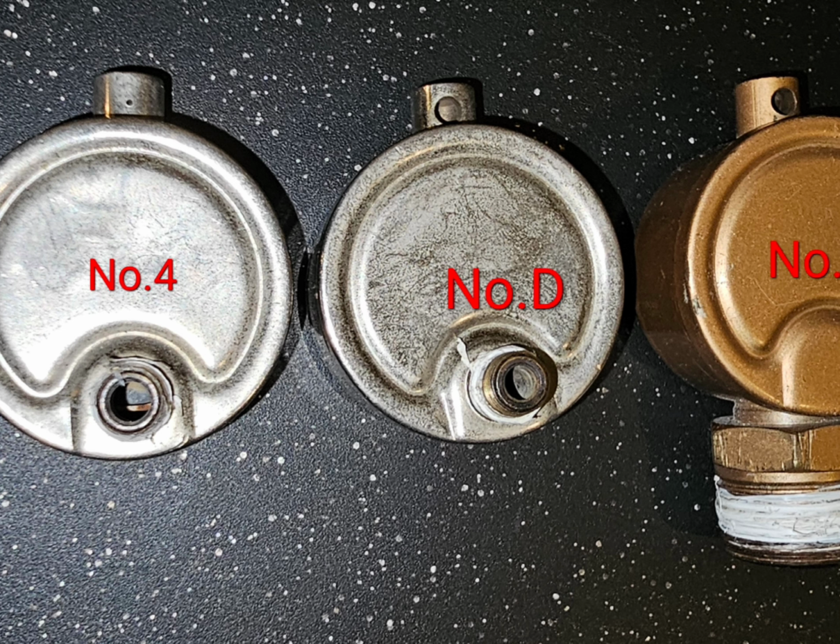So with that being stated, the problem with the steel convectors, and the video that I did years ago, as I'm actually sitting in the room right next to this thing, the air vent was opening up or cycling in and out. And this is as the system was on. It was pressurized, everything. But the vent would cycle in and out periodically. And the reason why it would do that is because the convector would actually start to lose its temperature.